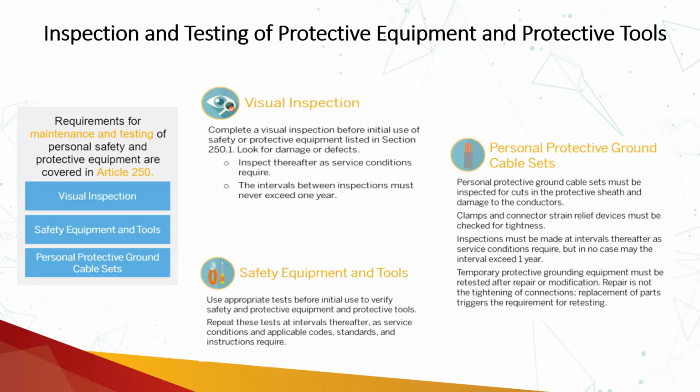For every tool and protective tool, they have set a certain test interval. What you are going to do is just read it and highlight those test intervals. For gloves, we know that it should be every 3 years. For blankets, it is different. And for other types of protective tools, the testing duration is different.